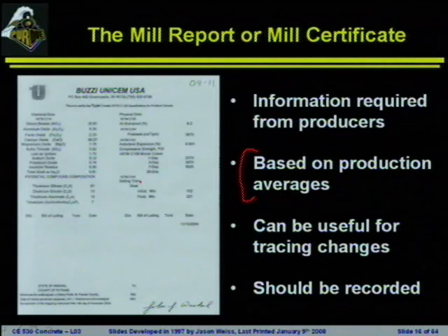This is becoming increasingly important in places where the clinker may not be produced locally. You'll remember last time we talked about the fact that once you get some of these materials, they can be shipped on water fairly inexpensively. And there are a lot of materials that will be produced in other countries and shipped into the U.S. What typically happens is the clinker is shipped into the U.S. and then there's a grinding terminal or a grinding facility where these powders will then be manufactured.